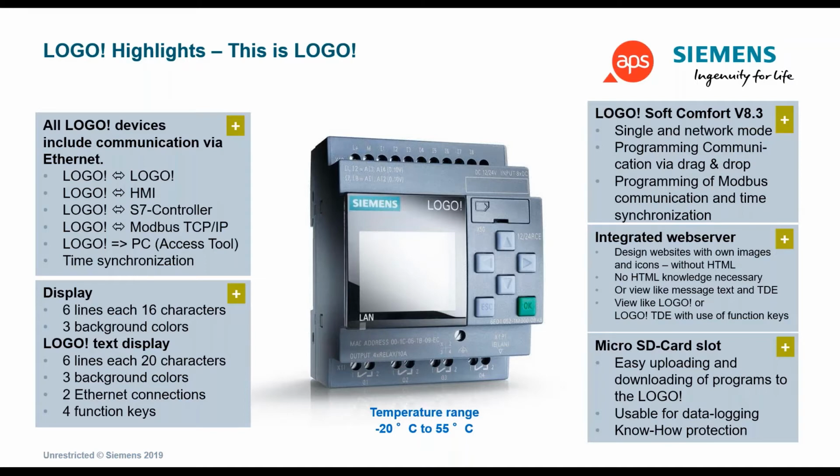One very important point is that the LOGO has an Ethernet connection straight on board. So with a standard patch lead, we can connect this directly to our computers for programming capabilities. In the event that we are doing volume sales or an OEM type application, we have the option to use an SD card, which is on board, and by using the SD slot, which I'm identifying here with my mouse, we can decide to upload a different program, or alternatively, we can also use it for data logging capabilities.